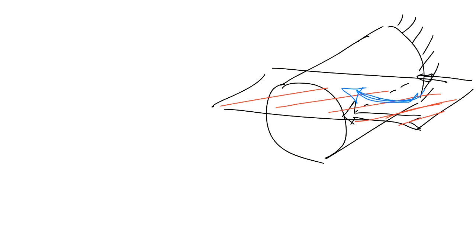In this case, you will be able to locate your neutral axis for the second case. Again, what is the neutral axis? What is the condition for the neutral axis? The first condition is that it should be perpendicular to the what? To the plane of the moment. But you have infinite perpendiculars to that plane. You can draw a perpendicular here or there or there. No, there is another condition, that this neutral axis should pass through the what? The center of gravity. So I can claim that this is the neutral axis for the second case. Okay? Clear, guys? Totally clear, Doctor.